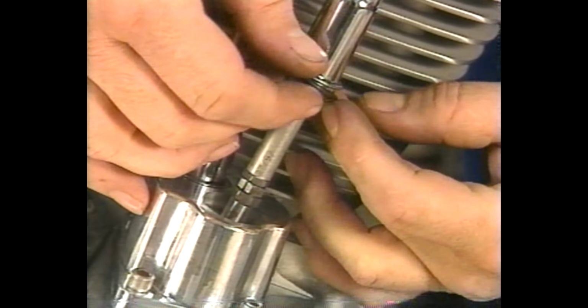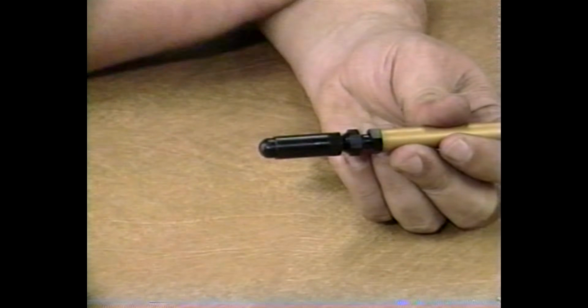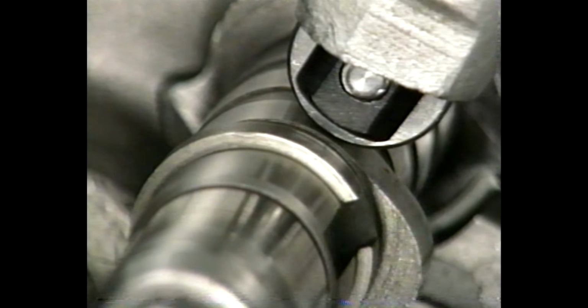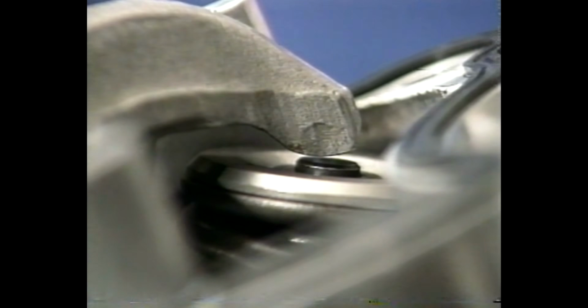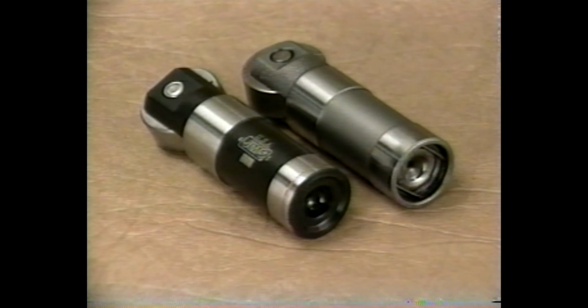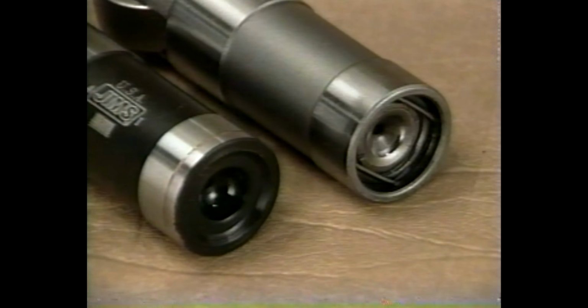We prefer to use adjustable push rods and non-adjustable solid lifters and keep the angles as close to stock values as possible. Solid lifters are also noisy and require constant checking and adjusting to ensure that correct valve backlash clearances are maintained at all times. We must also understand that not all cams are able to run both solid and hydraulic lifters. It is extremely important that we check with the cam's manufacturer to see what types of lifters their particular cam will accommodate.